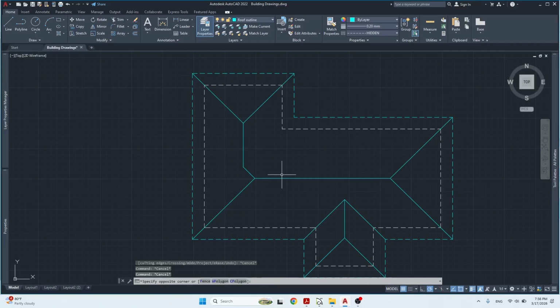So it comes as if we have this ridge, and then we have this hip rafter coming down from the ridge, and then it meets this ridge for the second portion. So it stops right there. It doesn't continue on. That's why we know to trim off this side. If you think of it that way, the highest ridge coming down meets the other ridge, and it stops, and this ridge comes across right there.